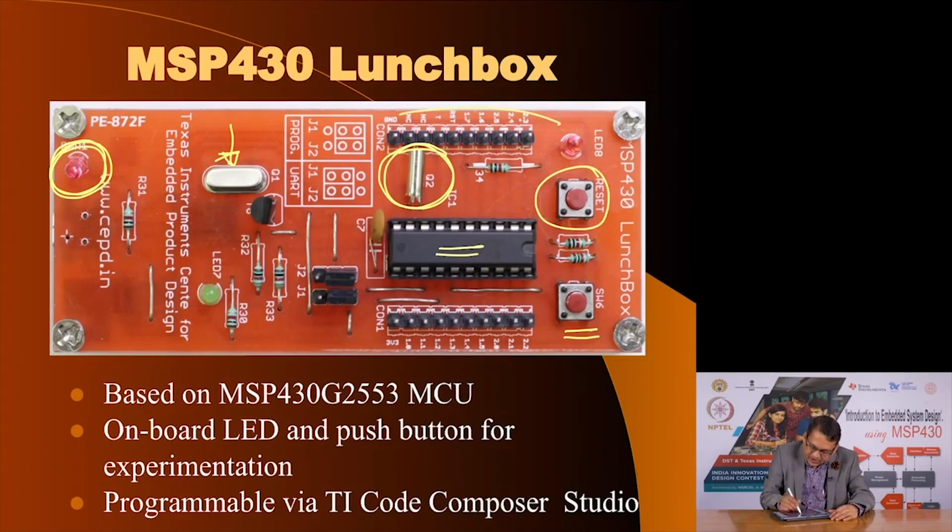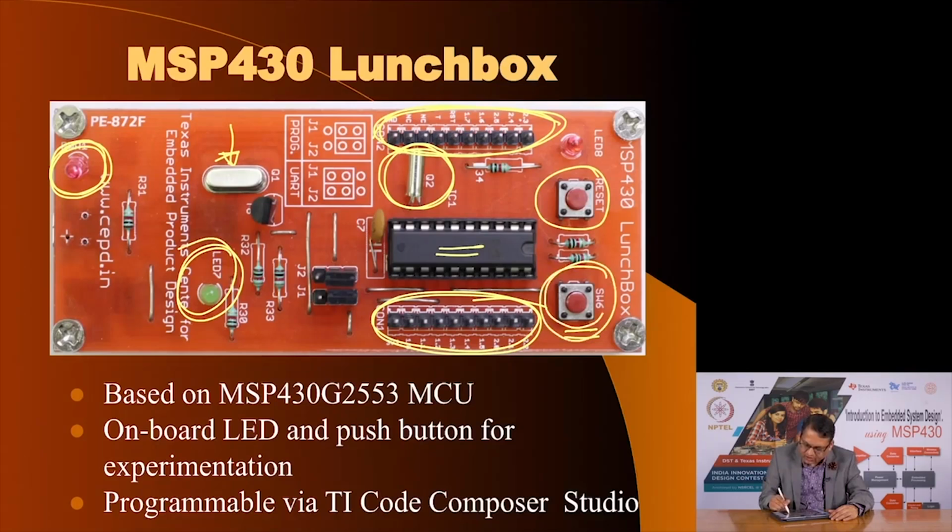The available pins that MSP430 offers you are available on these header pins, and this is the user LED here, this is the user switch that is connected to certain pins of the resident microcontroller, and here are some jumpers you have to engage in certain way as mentioned here. If you want to put the MSP430 kit in programming mode, which means you want to download code, then these jumpers have to be engaged.